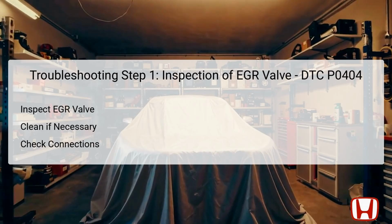Begin by examining the physical condition of the EGR valve, ensuring it is not clogged or stuck in one position. If the valve appears dirty or blocked, clean it thoroughly to restore functionality. In addition to cleaning, check all electrical connections and wiring harnesses related to the EGR valve, ensuring they are secure and undamaged. Any faults in connection can lead to communication errors that cause the P0404 code. If issues are found during this inspection, repair or replace as necessary.